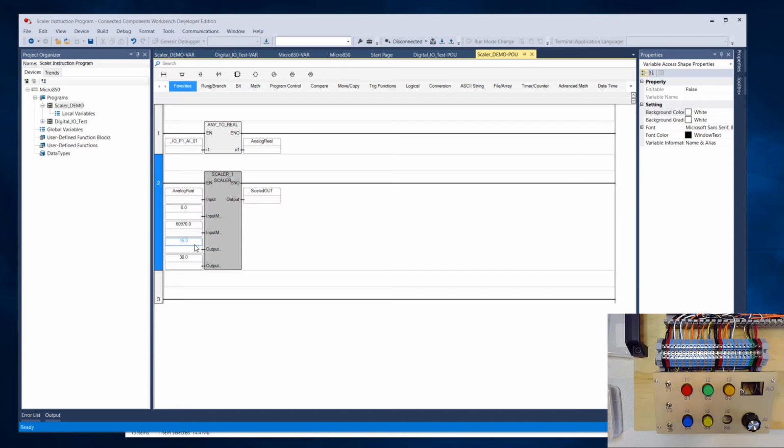So let's say we have a toggle switch that controls whether we're in the fine control mode or the speed mode. With the toggle in one position, we want our speed to be, let's say, 0 to 5 RPM. And then when the toggle's in the other position, we want the potentiometer to be adjusting our main running speed, and let's say maybe in that case it's between 30 and 40 RPM. So we have two different speed ranges, one potentiometer, and we want to be able to switch back and forth between those. Not a whole lot more involved there, but a little bit.